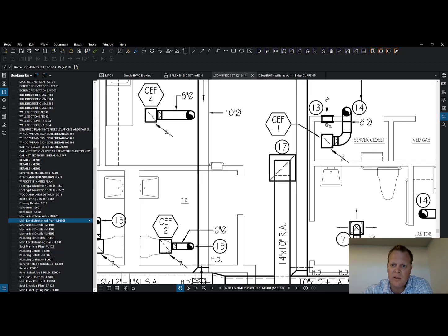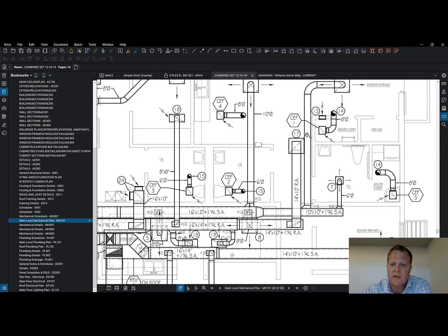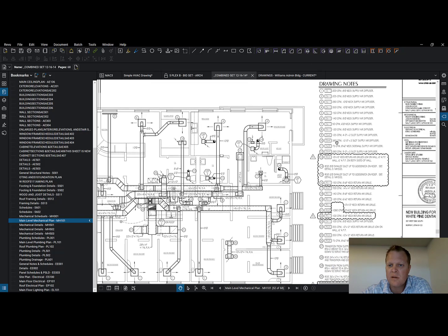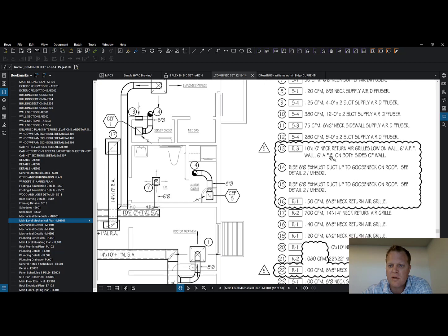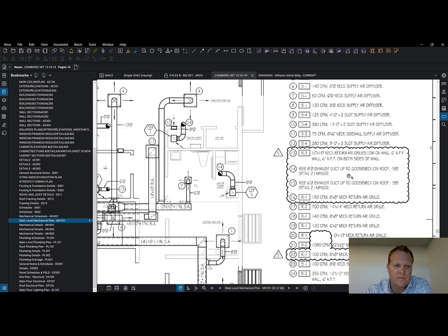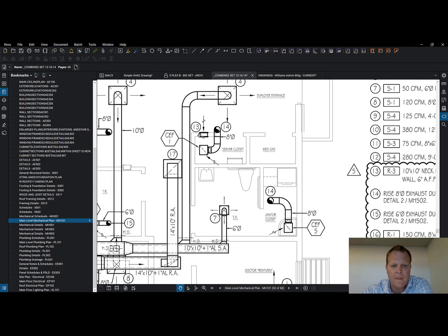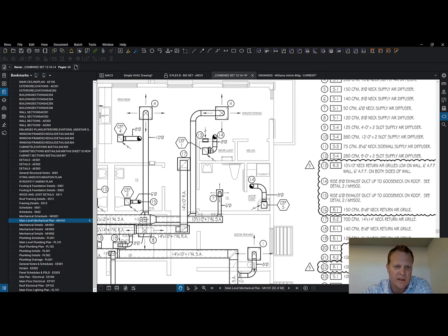This is kind of cool. Look at this little thing. That's an air transfer device, 13. Air transfer. Return air grill on wall. Well, it's air transfer in my mind. It's just moving air. It's just a hole in the wall. That's two grills on the side of the wall, on each side of the wall, that's allowing air to go through the wall to get into this space, because they're not trying to do anything. They're not conditioning the space. They're just letting the air from here get into here.